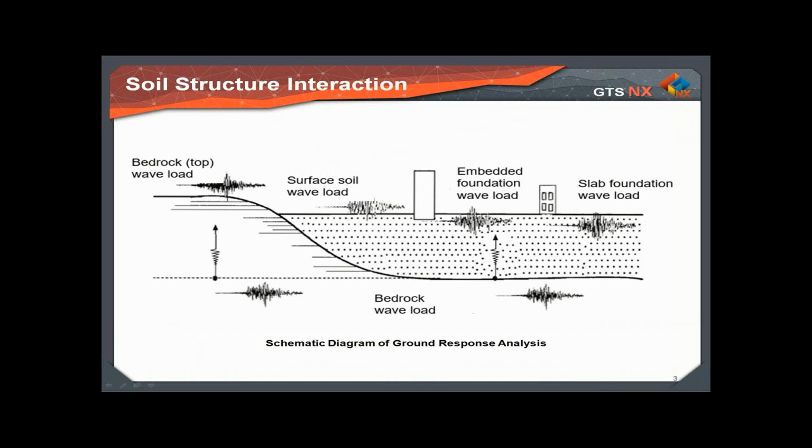Soil structure interaction is the phenomenon in which the response of soil and movement of the structure influence each other. When external forces such as earthquake act on these systems, neither structural displacement nor ground displacement are independent of each other. Unlike an above-ground structure, the response of an underground structure subject to an earthquake is mainly controlled by the ground displacement.